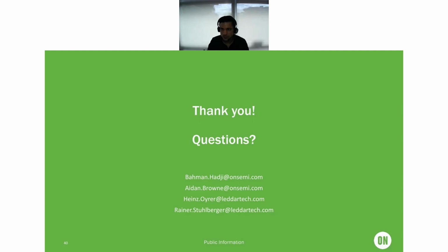Exactly. Thank you. First of all, for an APD, definitely we need a transimpedance amplifier because the output there is the current. And that's why, as Aidan said, when we started this project, we focused first on the standard output because it was the current output. But nevertheless, by using the TIA as an inverting amplifier, with an external resistor connecting it to the fast output, we could see the advantages of increasing the pulse width to make it compatible with the sampling frequency of the ADC.